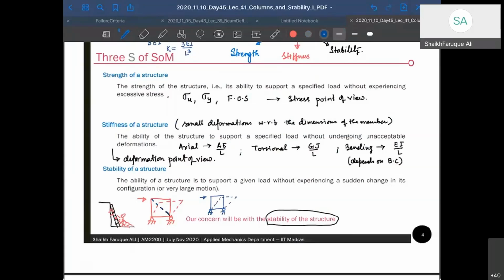So what you do, you just move the ladder a little bit, you perturb the ladder from its initial position, whatever its current state, and see whether the ladder falls down or not. If the ladder falls down, then it is not stable. But if the ladder goes back to its stable configuration, its original state, then you know that if you go onto the ladder it will not fall. The frictions are good enough, right? This is how you check.